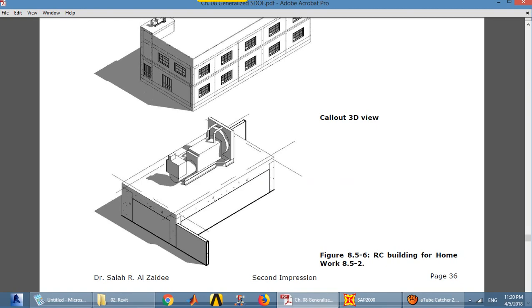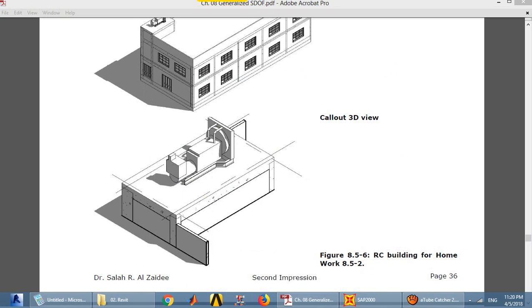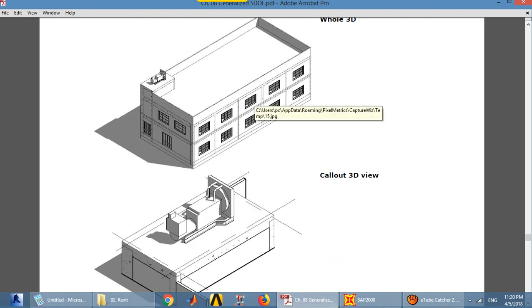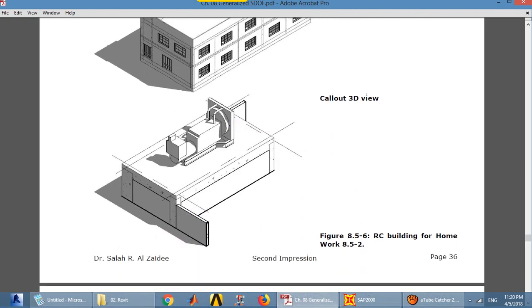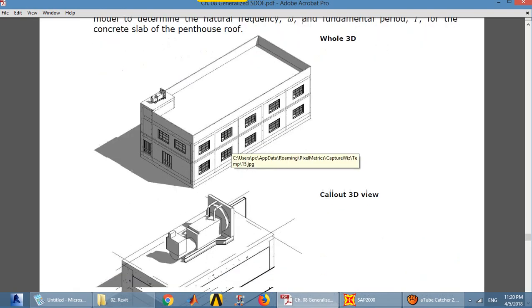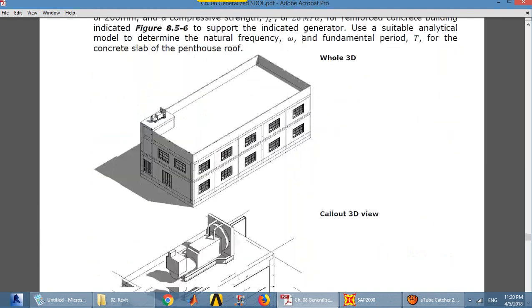That means we implicitly neglect the torsional stiffness of spandrel supporting beams and the interaction between the deflection of the slab and shortening of the supporting columns. These assumptions have been included in the finite element model to be able to compare with the analytical solution.